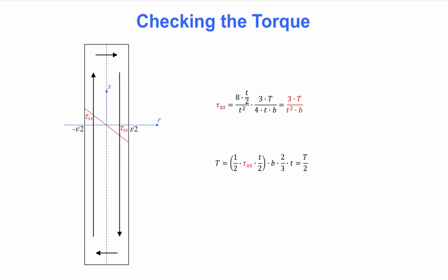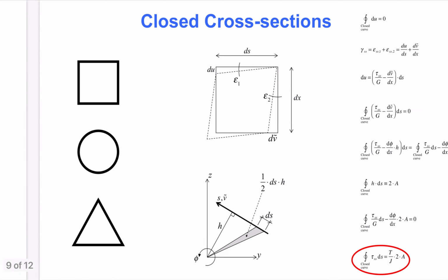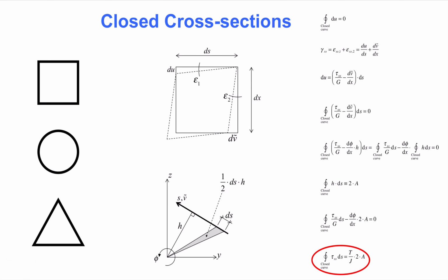Before we leave this slide, we may ask if other stress functions would be possible. The answer is yes, but many of them give stress distributions that appear unphysical. Consider, for example, a triangular stress function with its peak at the midline of the cross-section. The constant slope on the sides of the triangle implies constant stress, with a discontinuity at the middle of the cross-section. That appears unphysical. Instead, we might contemplate half a sine wave as a stress function. That would be better, but still not as likely a stress distribution as what is seen here for the quadratic stress function.